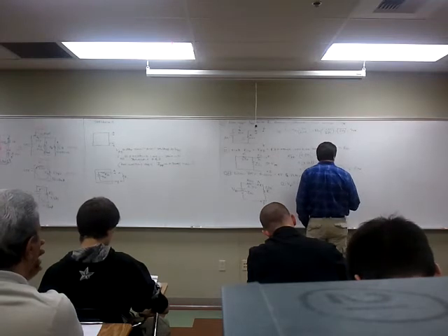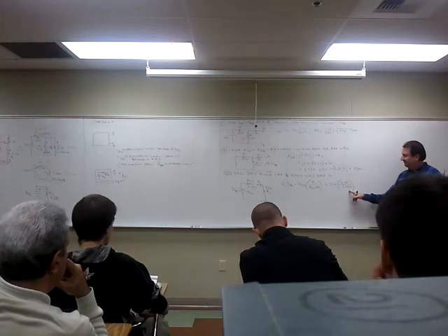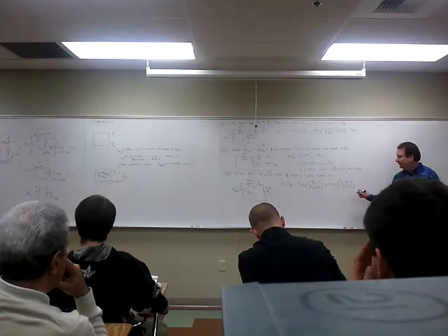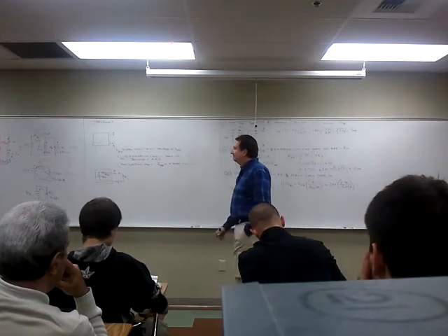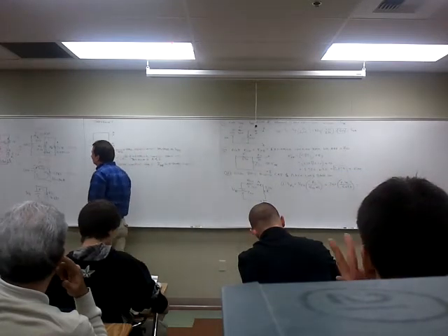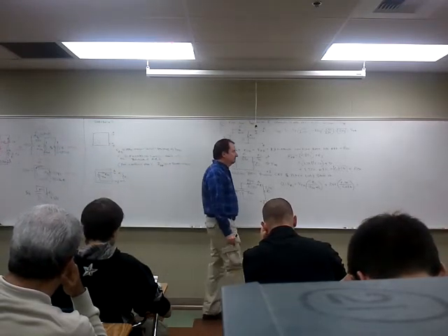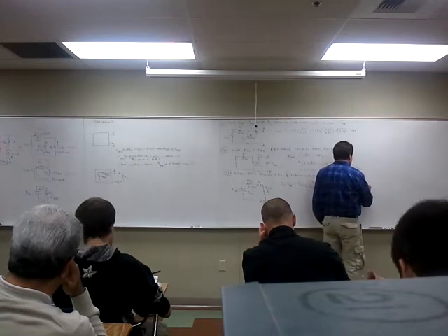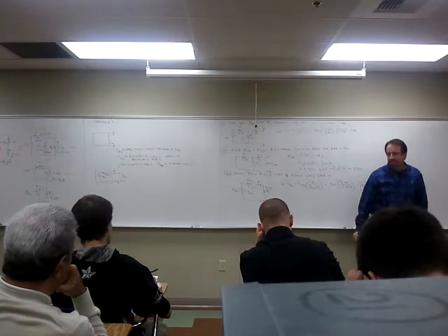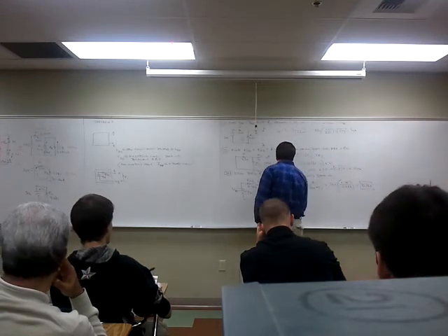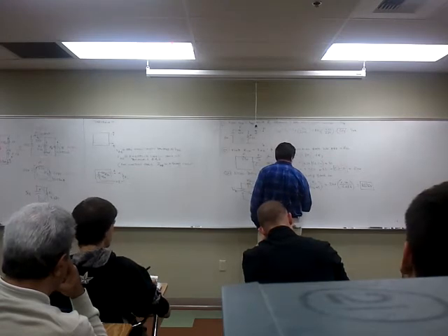5.02K. So on your calculator, you go 2.7K divided by 5.02K equals, and then times 20, and what do you get? 10.76. I bet you get 10.76 volts. And then to find the current through the load is simply the voltage divided by the resistance. I is equal to V over R.